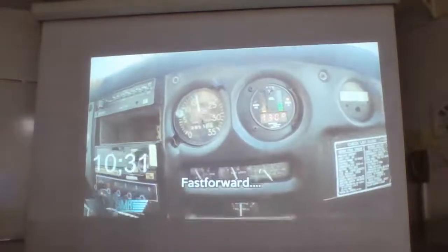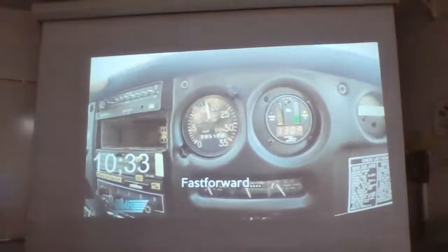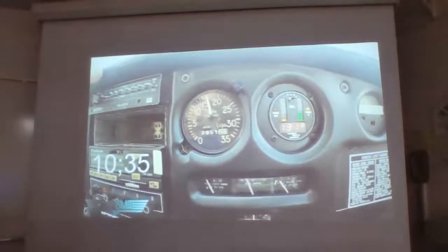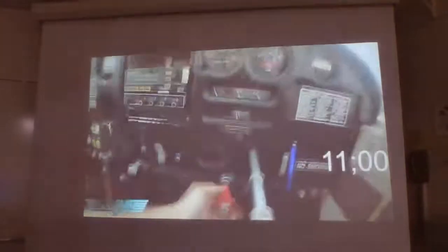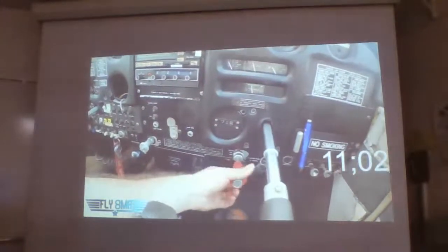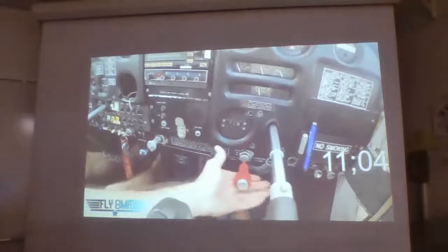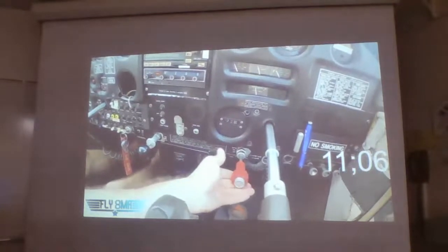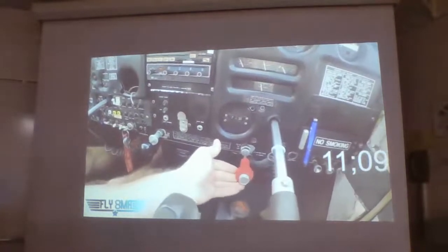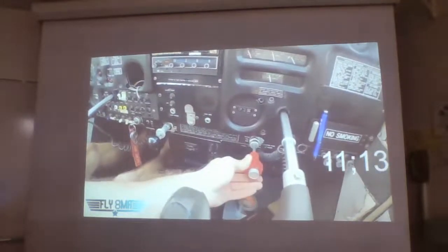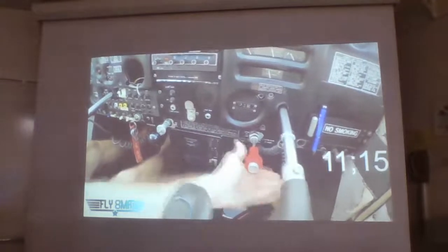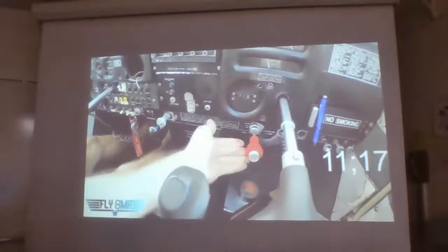All right, this might be it, guys. We're losing a little bit of RPM. Coming off 1800 down to 1700 RPM. Starting to shake pretty good. Try playing with the mixture and see if we can get any more power out of her. Oh, no, didn't like that. Let's go ahead and lean it out a little bit. There, she's coming back for us. 1500. For some reason, it likes being a little bit leaner here.